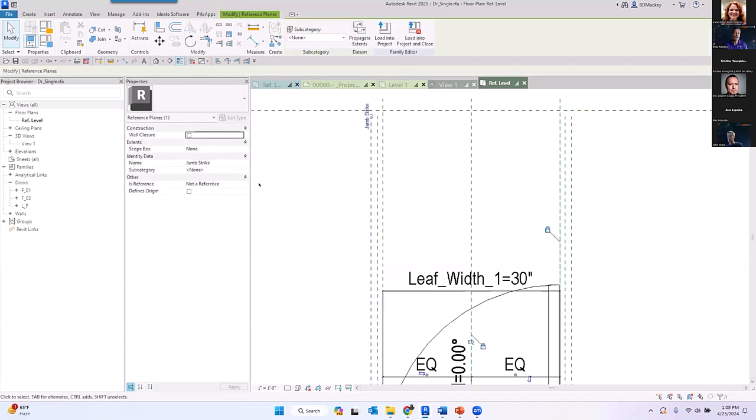There's also the capability to say there's a strong or a weak reference. In way older versions of Revit, there was a big difference between strong and weak. You would only get instance-based shape handles, like if you had an instance-based parameter, if it was set to be strong. If it was weak, you didn't get those.